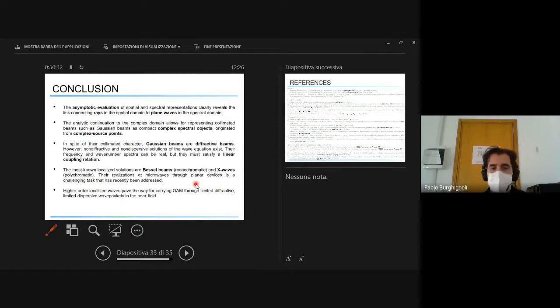I have talked a little bit about the connection between plane waves and rays to give a geometrical ray optics interpretation of the radiation from apertures, and this gave me the opportunity to talk about diffractive beams of the Gaussian type and non-diffractive beams, with specific attention to Bessel beams and X waves, that can have a lot of applications in the microwave range thanks to the focused and non-diffractive character.